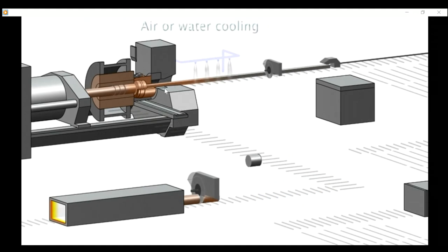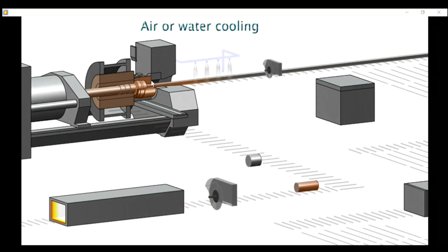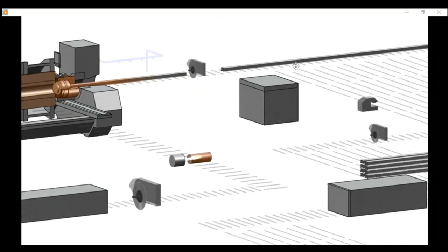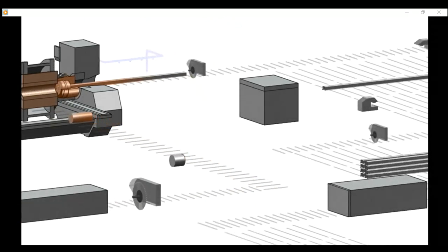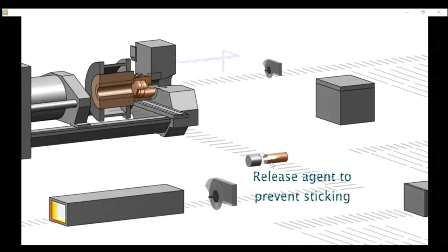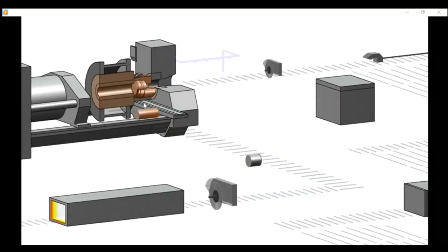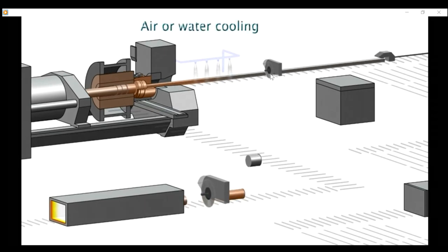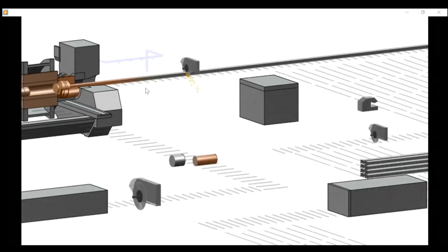We apply pressure. You see that it will be very long. Why? Because the cross section dimension changes, and it becomes very long, and then it is cut again. This is a pellet. We put oil here, then put it in a machine. This is a hydraulic system. They apply pressure. You see, it is small in length, but the extruded length is much, much longer because the volume is constant, guys.